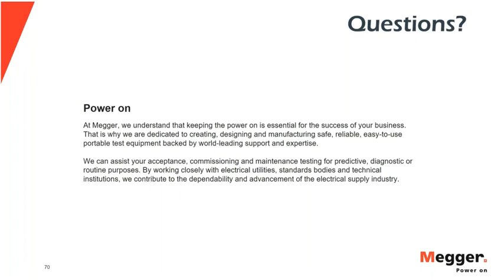Thank you, Diego. Next question is for Jill. What do you mean by electrical insulation health? Okay, that's a great question. Essentially, electrical insulation health represents how well an insulation is supporting an electric field with minimal losses, and the condition in which an electrical or any suitable insulation material does that is when it's very dry, when it's clean, it's contaminant free, whatever the source of those contaminants may be, and I've seen so many, that the material is relatively void free.